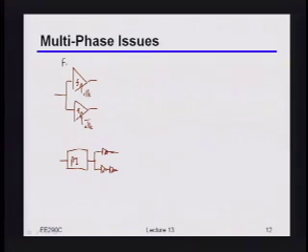So let's call this the full rate design. But let's say that we actually wanted to use multiple clock phases. So we wanted to do time interleaving because we want to run really, really fast, much faster than we could get an oscillator to run, or at least a ring oscillator. Let's take the simple example where you do what's called double data rate, often referred to as DDR.